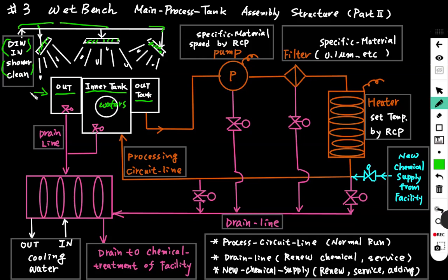And the process must be the DI water clean, can be tolerance. Some chemical solution cannot touch the DI water. So for that kind, we have another special solution to clean the tank. If your equipment is without this equipment, you have to use a DI water gun and clean the tank by manpower.